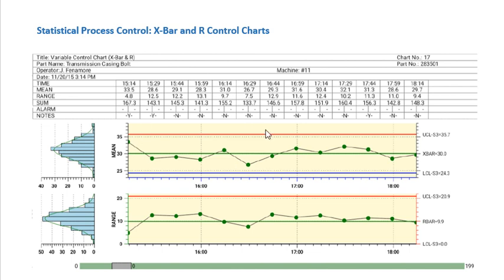And so this R chart, the range control chart, focuses on the range of values. That means the difference between the maximum and the minimum values in the subgroups of the data collected during that process, okay? And don't forget what range is. You get it by subtracting the minimum from the maximum, okay?